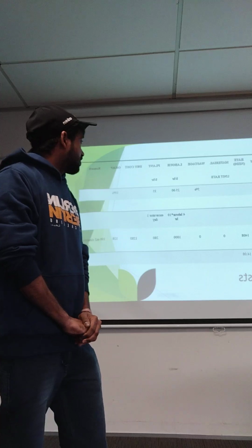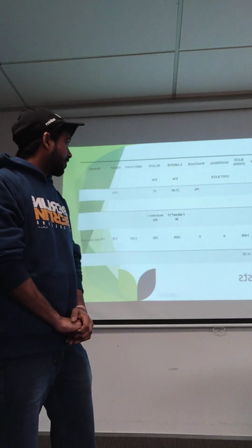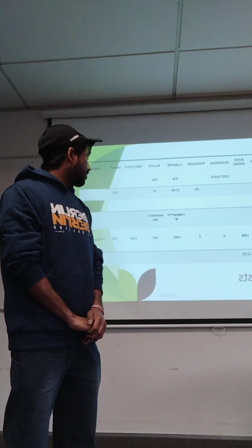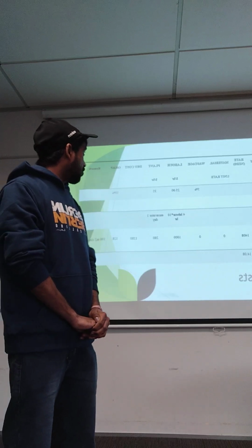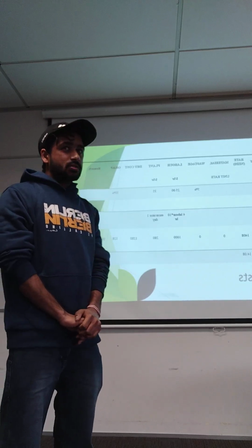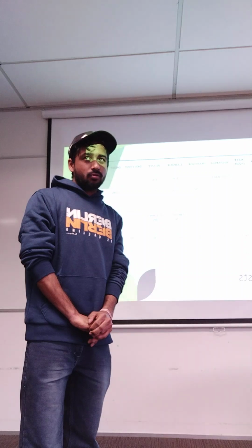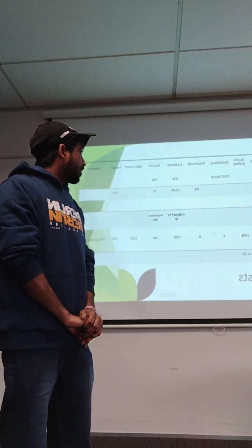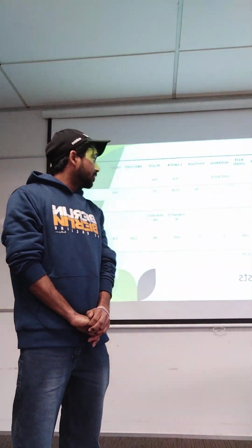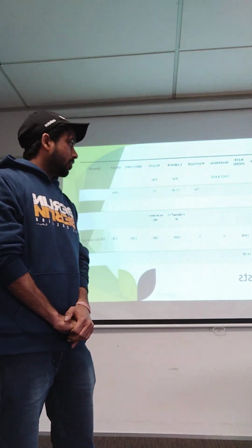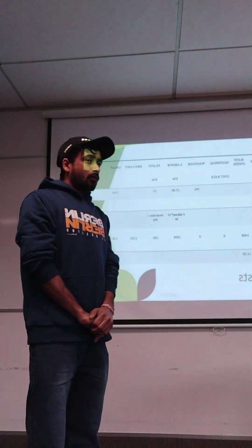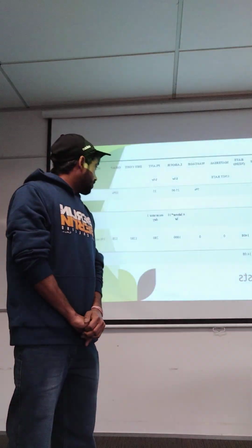There is some substructure which includes some quantities and measurements. Earthwork includes 5% of wastage, and labor rate is $25 per hour, and overhead expense is 10%. And ground clearance of 1 meter length according to the center line, in meter square, 100 meter square, which is 14.080.